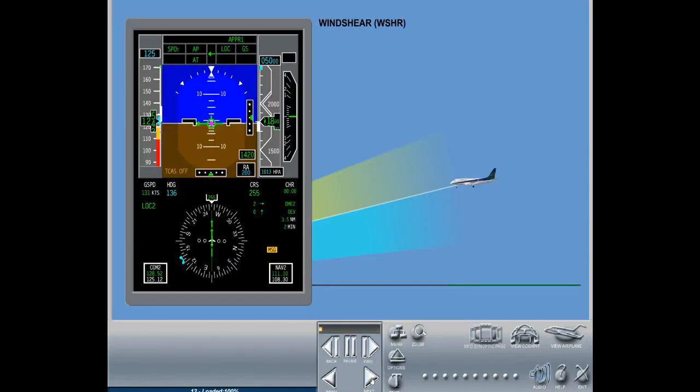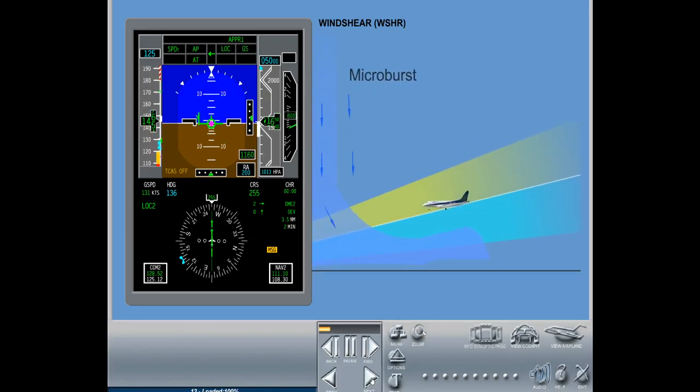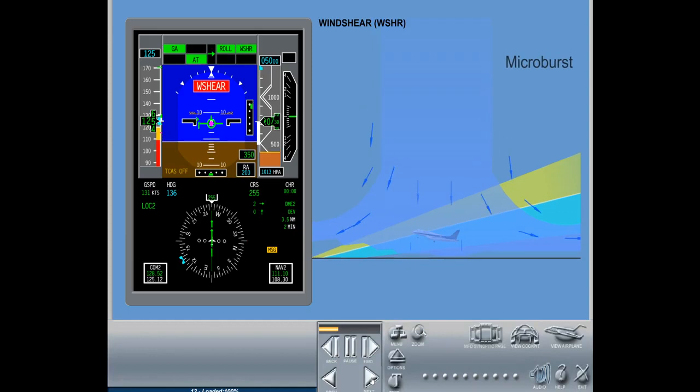Wind shear, WSHR. Although it is not pilot selectable, the wind shear protection system will display the label wind shear as the vertical active mode in the FMA during a wind shear situation. The system provides flight path guidance angle limited to stick shaker, wings level, and RO alert. Wind shear, wind shear, wind shear. Note that wind shear protection is disabled above 1,500 feet above ground level.